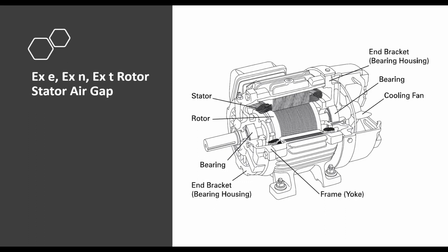Because if it goes back and the rotor has been changed at some point, because you don't see this piece of equipment every day for 5 years, if the rotor has been changed at any point for God knows what reason, and somebody's put a larger rotor in there, it fits, but it no longer has the gap that doesn't create a spark anymore. You are signing the equipment off and sending it out into the world saying it complies to the standard it was manufactured to. Make sure the paperwork meets the requirements of the standard it was built to.